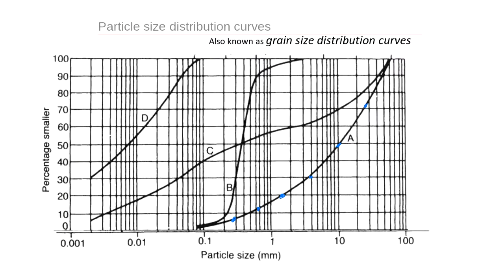Now what we can do is let's just do one of the soils. We're not going to do A and B because we already have some idea how to do that. Let's do soil C. And for soil C, we're not going to look at the table. We're just going to look at the curve. So it's something that you'll do tomorrow. I want to do a quiz. Okay, so let's decide how much gravel, sand, silt, and clay we have for soil C.